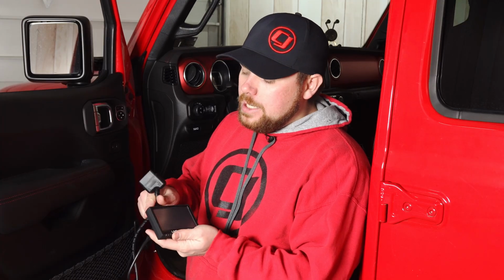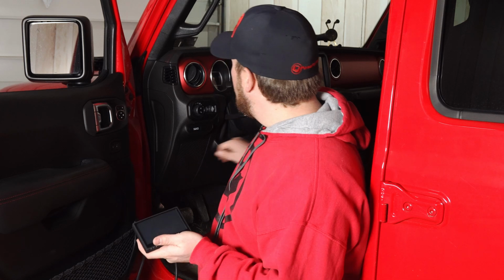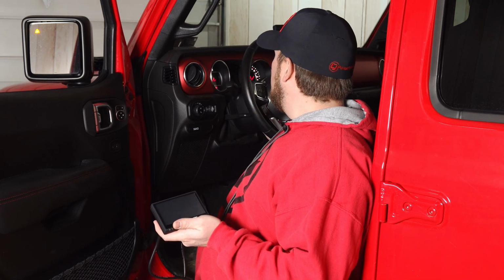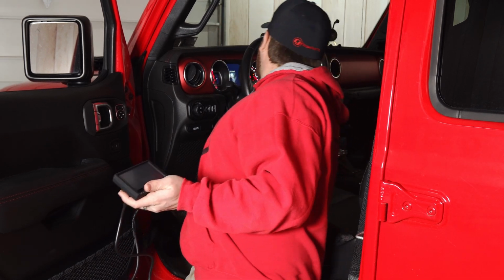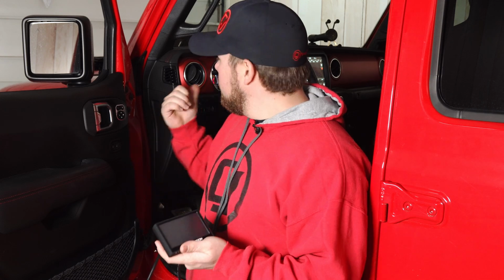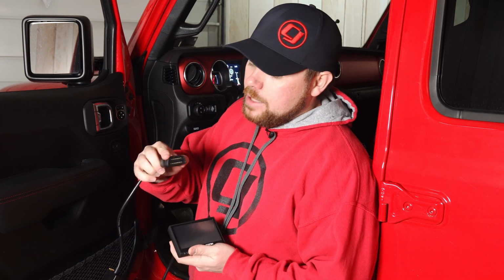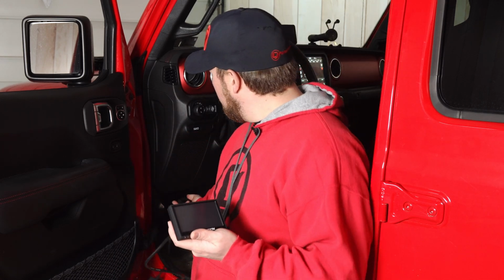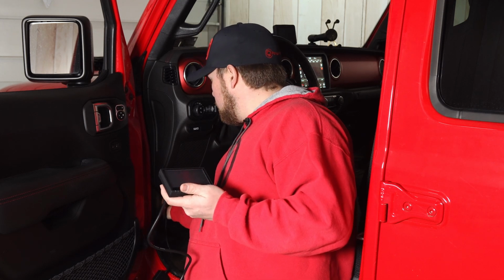But for right now, what we need to do to plug our scan tool in is put our key in the Jeep and turn it to the run position. Now, we went in the run position without the vehicle being on and the engine started up, so everything's beeping behind me. And then we will plug our OBD2 port right down below.